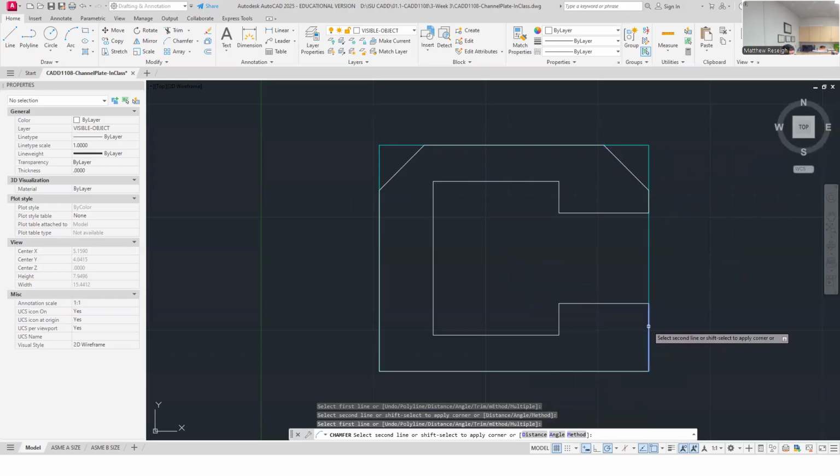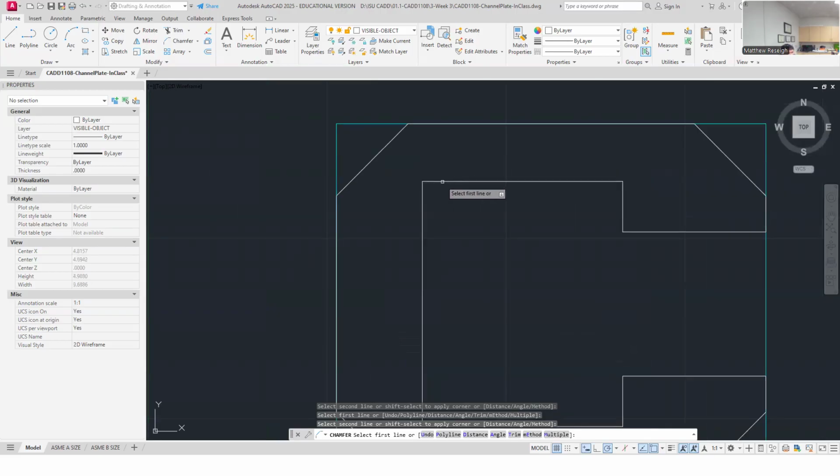So here's the next one that I want to trim, that one to this, and this one to this. And that's the outside 1 inch chamfers. So I'll escape this command. However, I could come into the inside. This was kind of a subtractive chamfer. If I chamfer an internal feature like this, it should chamfer to add kind of an additive chamfer here. So let's see if that works.